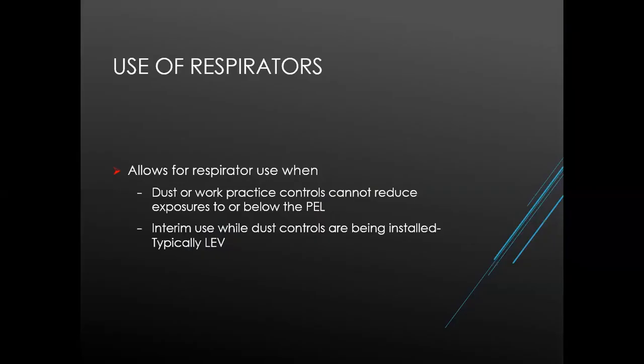Respirators are to be used when engineering or administrative controls cannot reduce a worker's exposure to below the permissible exposure limit. They are also to be used during the interim installation of engineering controls, such as local exhaust ventilation, and where exposures exceed the PEL during tasks, such as certain maintenance and repair tasks for which engineering and work practice controls are not feasible.